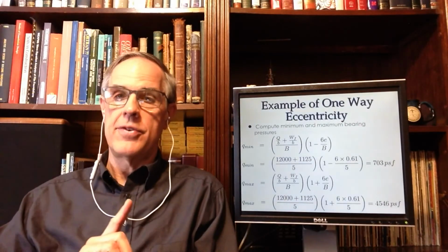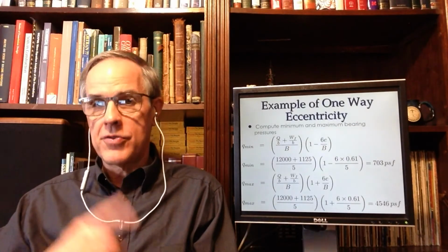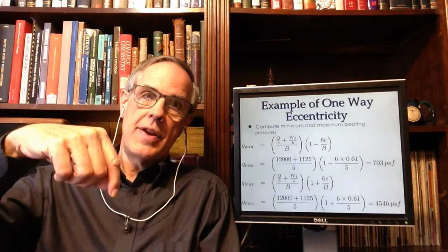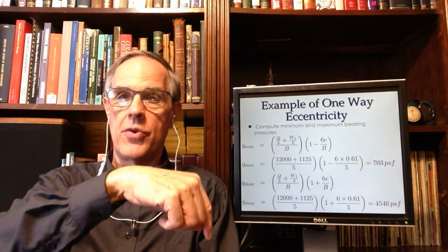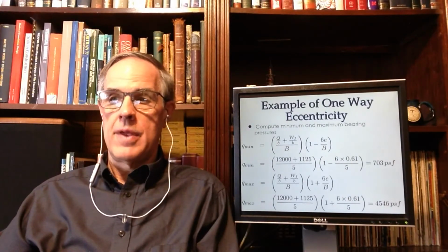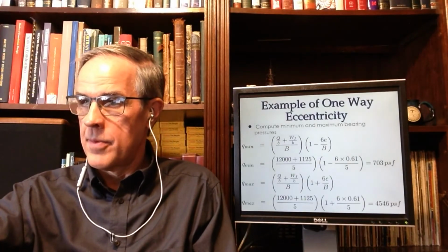Now, in some cases, instead of giving you a moment and having to do the intermediate step to eccentricity, we will tell you that this load is so far off of the centroid, and this is the eccentricity, and you can compute those.